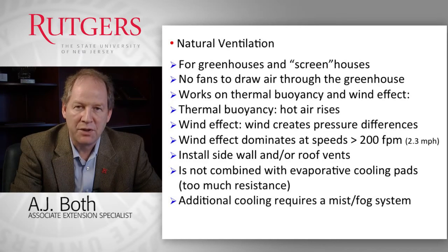The wind effect is typically the dominating force. As long as the wind is blowing at more than 200 feet per minute or about 2.3 miles per hour, which is not very fast, then the wind effect dominates. So only under very wind-still conditions will the thermal buoyancy or the stack effect have a major impact on the ventilation rate.